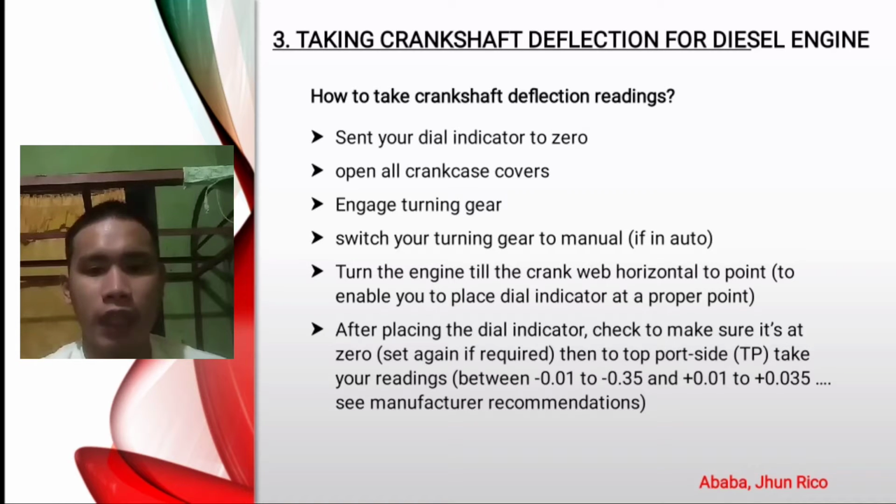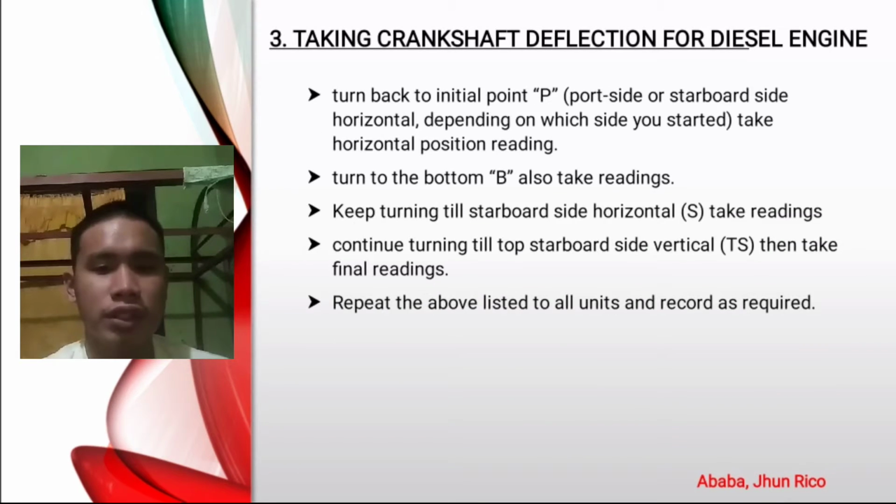Fifth is turn the engine till the crank web is horizontal, so that it will enable you to place the dial indicator at a proper point. Sixth is after placing the dial indicator, check to make sure it is at 0. Seventh is turn back to the initial point. Eighth is turn to the bottom, also taking readings.